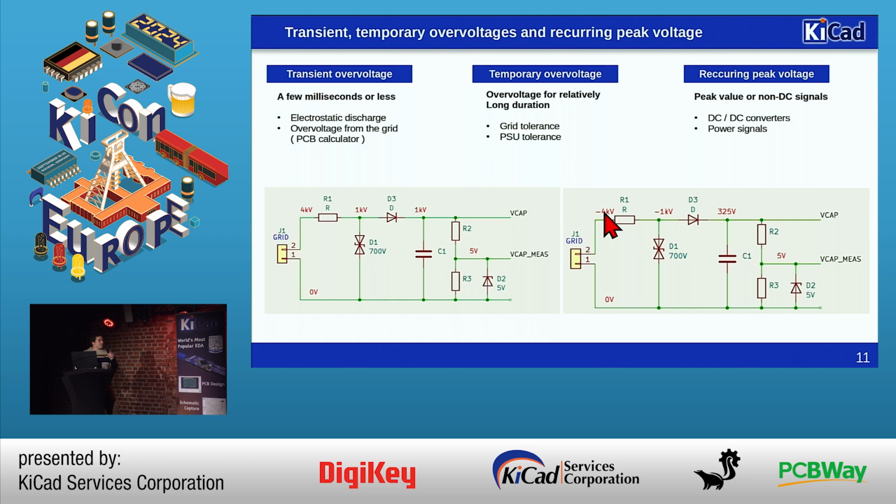We have to do this with the negative too. And with the negative, this diode, that was no issue here. Now there's 700 volts. So we need a clearance of 700 volts from here to here, so a clearance that corresponds to 700 volts. And basically we do this for all the schematics. We try to group it by net classes, and we define the voltage that can come across net classes.